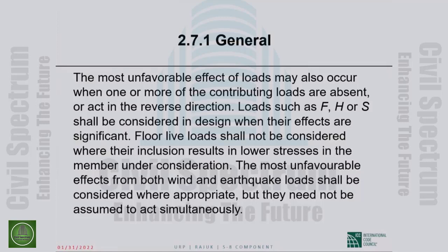The most unfavorable effect of loads may also occur when one or more of the contributing loads are absent or act in the reverse direction. This is extremely important. Most unfavorable effect may occur when one or more of the contributing loads are either absent or act in the reverse direction to that of the other loads.